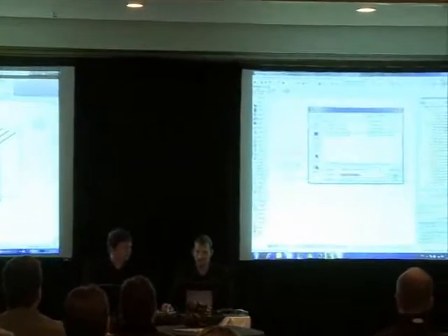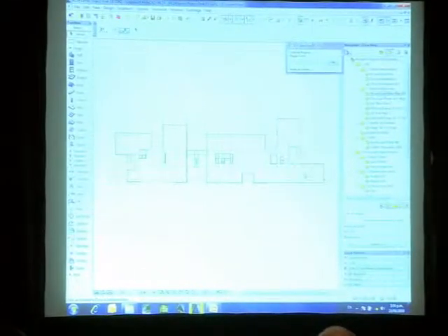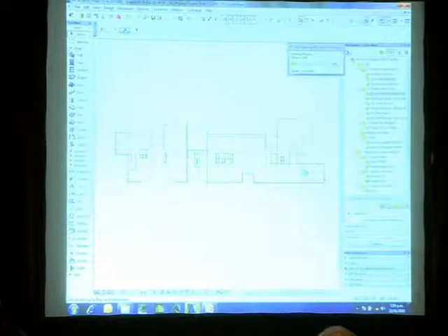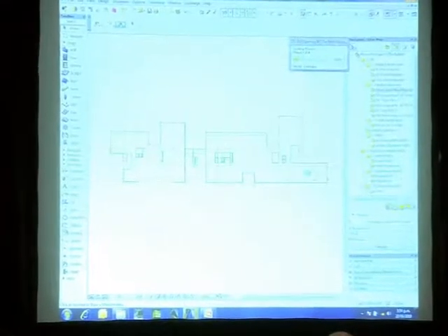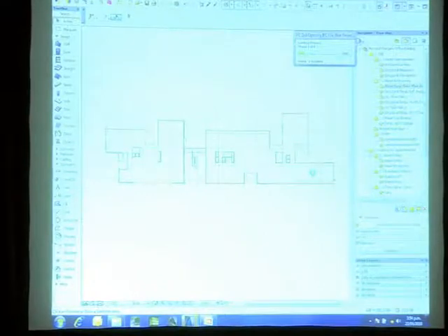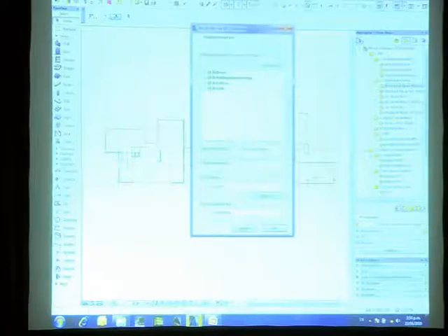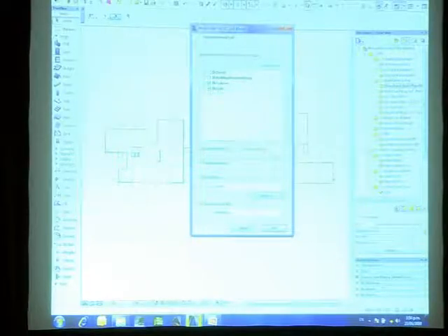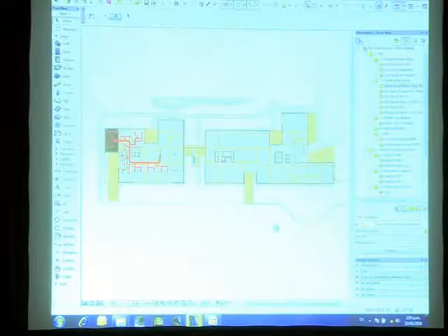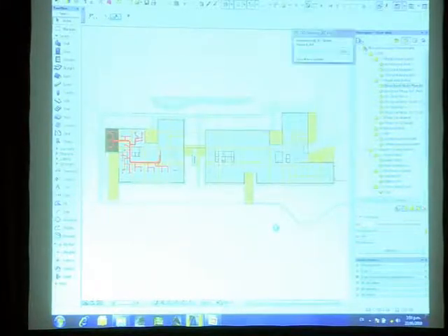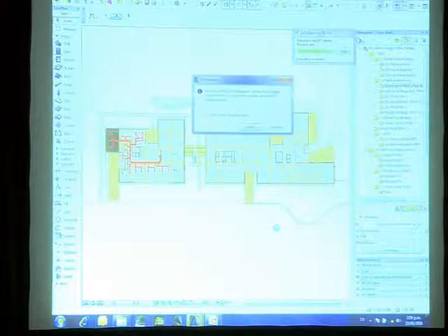And then open. And now, within a few seconds, you will see, if we did it correctly, I hope, yes, we didn't miss anything, then a dialog will come up and ask a few things. Here, as you see, it asks whether you want to merge everything that was exported or only, I would say, only the columns, because those were changed by the engineer. So I will say okay, and then it comes into ArchiCAD.